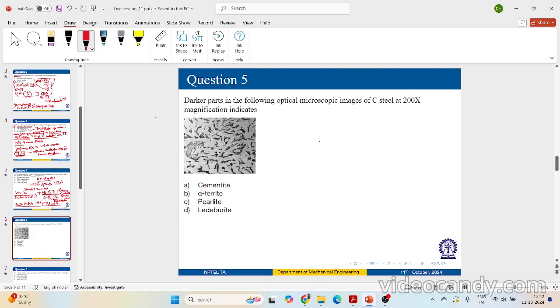Next. So if you see these high strength low alloy steels, they are usually welded in the as rolled or some normalized condition. So people do normalizing, right? Heat treatment, normalized heat treatment. So either they do welding in the as rolled condition, or if you have done normalized heat treatment, that will also be done for this high strength low alloy steel. And the weldability, if you are thinking of the weldability of HSLA, this is more similar to mild steel only.